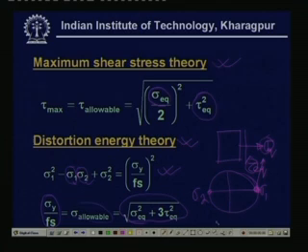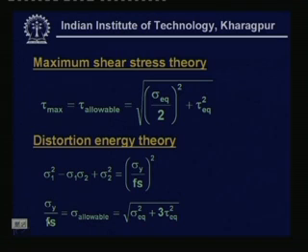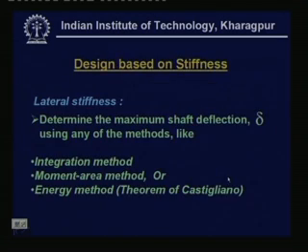Normally what happens is that most designers opt for the maximum shear stress theory, because as we have seen, it is more conservative compared to the distortion energy theory. But anyway, the choice lies with both theories. Now, this is a design based on stiffness.